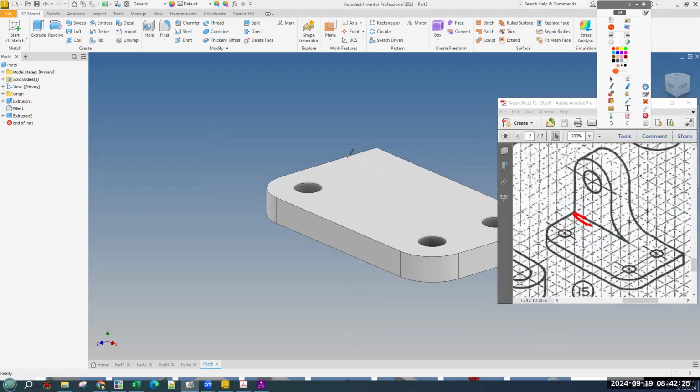We're going to draw a footprint on this face here that is going to be 2 by 4 and extrude it up whatever the total height is. We aren't going to worry about this edge here because this sloped face right here is a fillet, even though it's sort of an interior edge. So far, we've only filleted outside edges that made it round over. Here, we're going to fillet an inside edge, and it's actually going to create material, but more on that later.